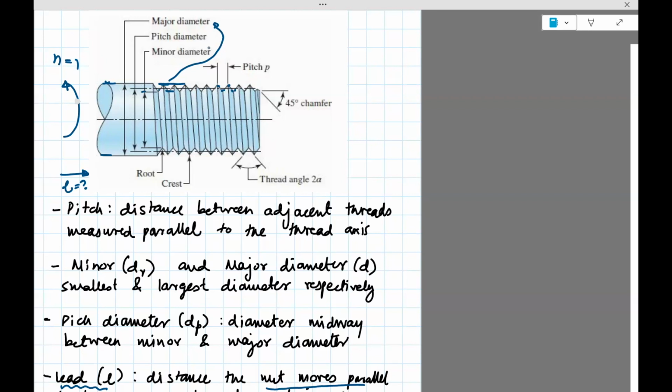And one of the things about fasteners, or power screws, is that it converts rotary motion to linear motion. So the spinning is translated to linear motion. And this is good because mostly you have motors which are turning and spinning in circles, and many times the load which needs to be moved is moving back and forth. So this one will achieve that kind of motion.